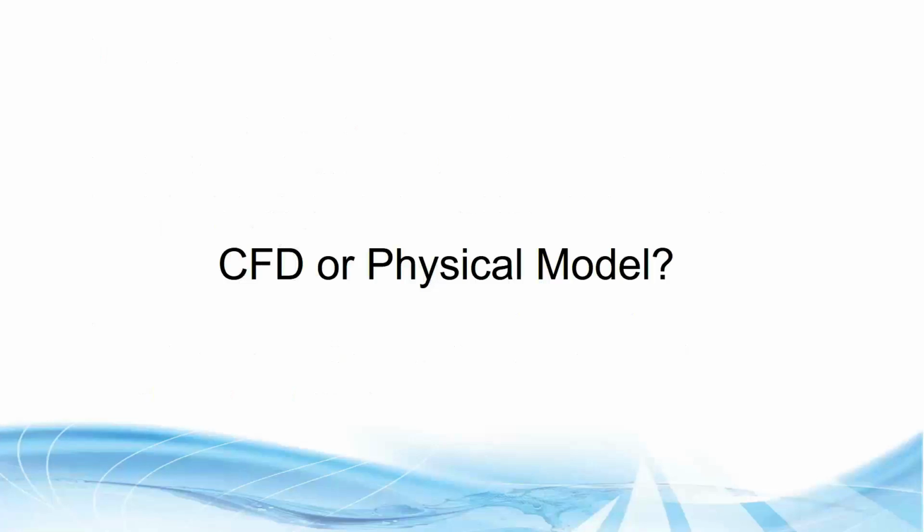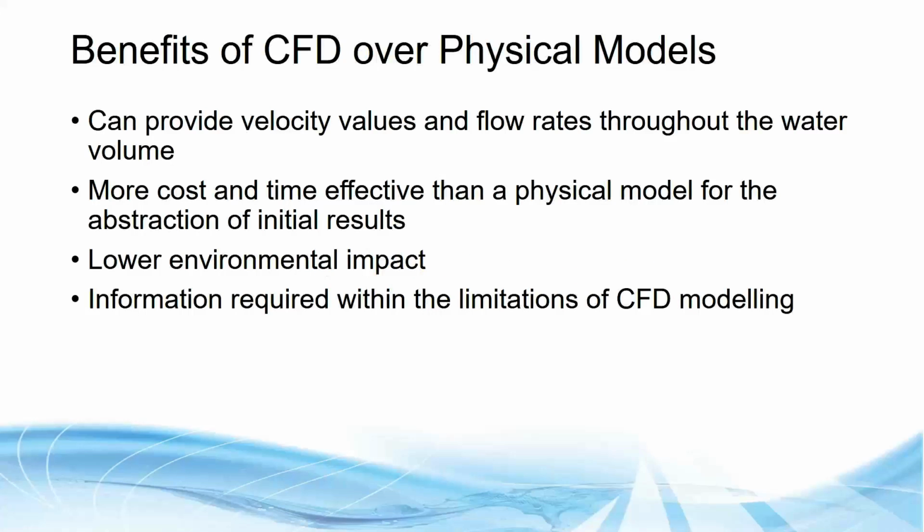So we had an internal discussion within the company as to how we're going to approach this, CFD or physical model, and I recommended, based on the data that the client required, so velocities and a flow split, and the fact that they were under time constraint, they required information quickly, efficiently and reliably, that a CFD model would be perfect for this situation. The reasons are that a CFD would allow us to provide velocity values throughout the entire water volume, throughout the entire chamber, and a flow split as well. It is much more cost effective and time effective as well compared to a physical model.